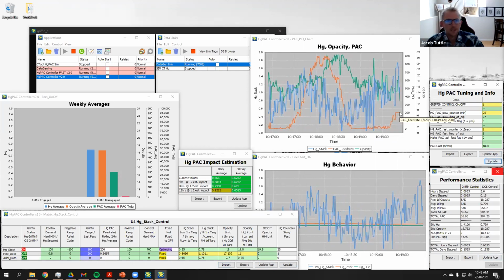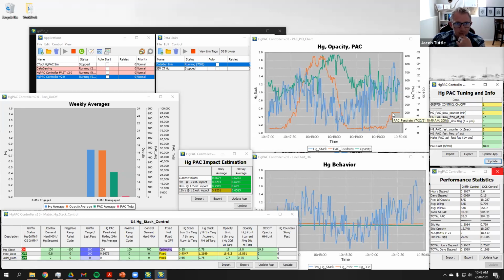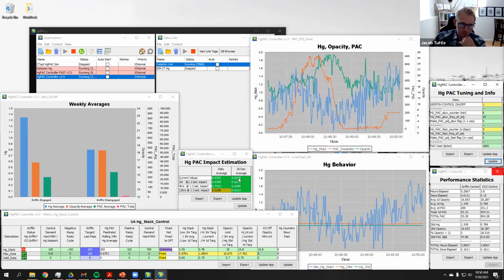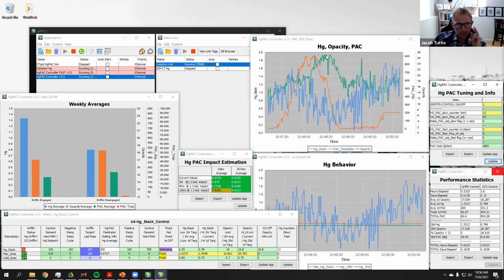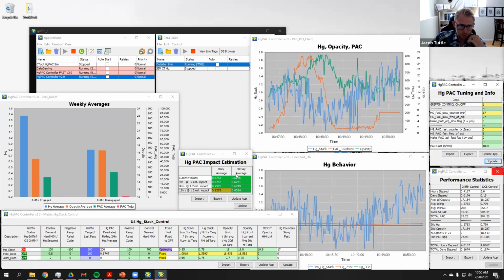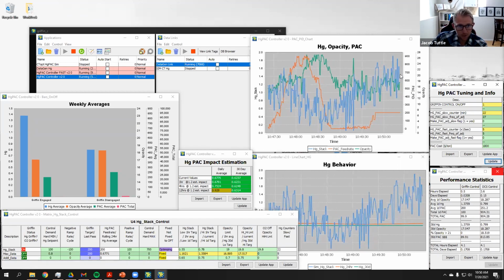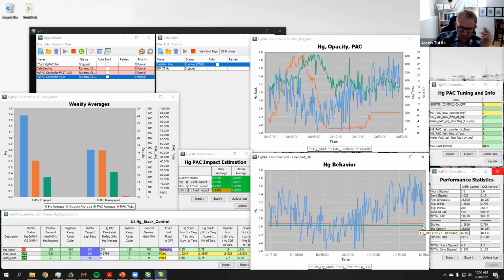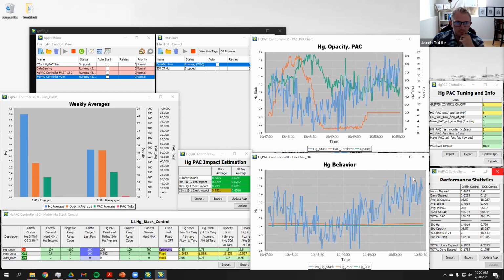And so rather than immediately responding to fluctuations in mercury, our system recognizes that this is the value that really matters. And so there's no need to start chasing mercury around and upset the process by realizing high opacity measurements and values when there's plenty of room on the value that we're concerned with. You see, even though mercury is higher at the moment, our 30-day average, which is also this green line down here, you can't even see, it's indiscernible, the change to it because of these couple of moments of high mercury.